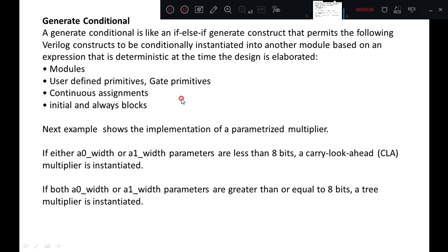Okay. We'll understand what is elaboration. Elaboration means when your text code is executed, at that time the text code should be linked with the library files required and the operators that are defined. So the entire thing, linking of all library files along with your text code, we call it the elaboration step.